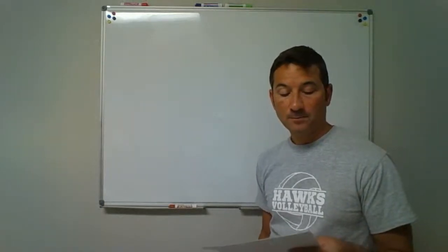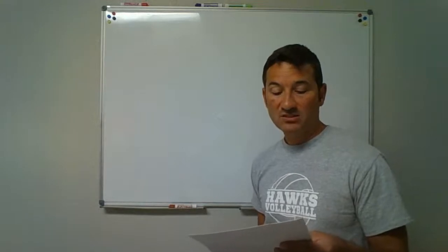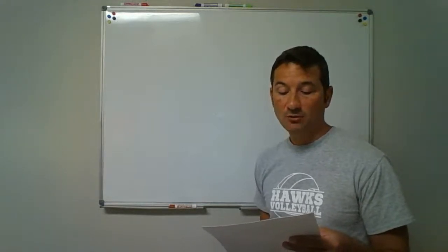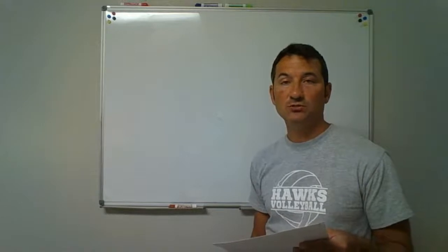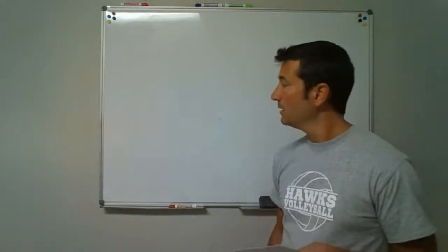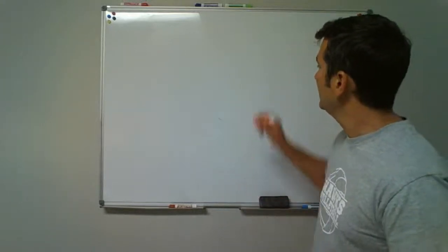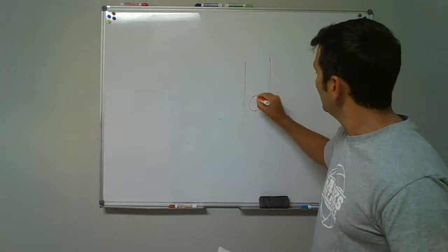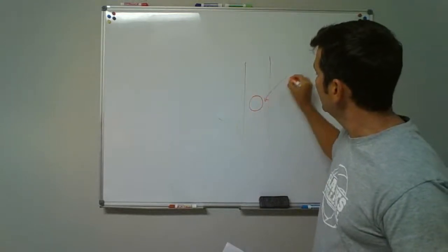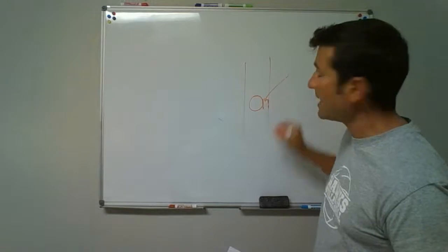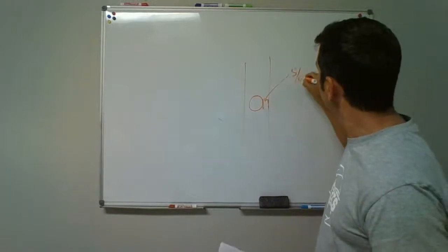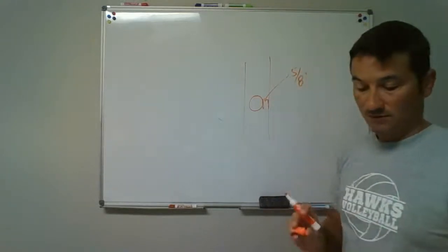Number 5, what is the minimum distance required from the edge of the bore hole to the edge of the stud? We drew this as a picture as well. We drew the stud, drew the hole, and said, what was this area, from the edge of the hole to the edge of the stud? Got to have at least 5/8 of an inch. 5/8.